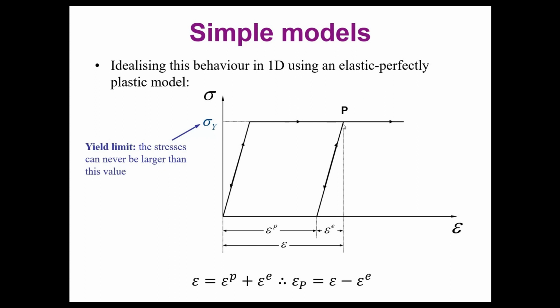And it's able as well to manage unloading and reloading processes, capturing the plastic deformation, because of the introduction of this second horizontal line in here, that apparently is super simple, but is able to capture something important: the change in behavior from elasticity to plasticity, and the permanent deformation that we are not able to capture with the isotropic linear elastic model that we have been using before.